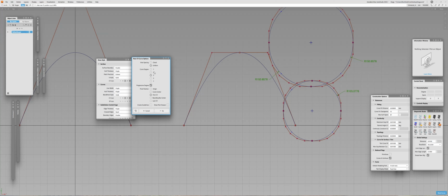This chord and uniform describes the mathematics, but it doesn't describe the reasoning. Now, by default, Alias always has uniform spacing turned on for all of the tools and for the curves as well. So it is uniform. Chord is an option. And if you don't touch it, that's fine, but at least you have an option.